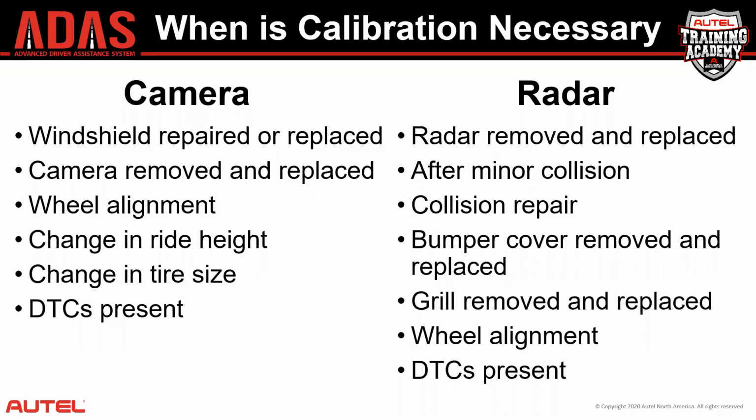Maybe it hit a pothole and now it needs an alignment. Vehicle comes in to a shop, the alignment is performed, and the thrust angle is adjusted back to the factory setting of 0.0 degrees. Since the camera was calibrated before the pothole, why would I have to recalibrate it after I aligned it? Here's the answer.